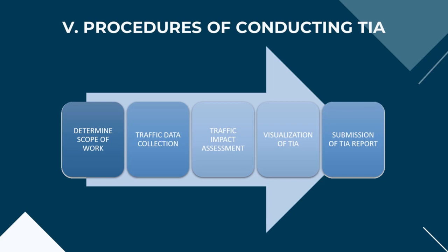Primary traffic data consists of data obtained firsthand by the traffic consultants, traffic planners, and engineers. These sets of data are commonly obtained by traffic surveys performed on-site or via technology that allows automated data collection, such as AI-based video analytical data collection, technical traffic sensors, and etc. Secondary traffic data is obtained from existing road traffic volume data obtained from the government, the local authorities, and/or past traffic analysis studies.